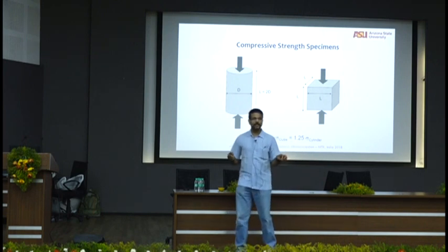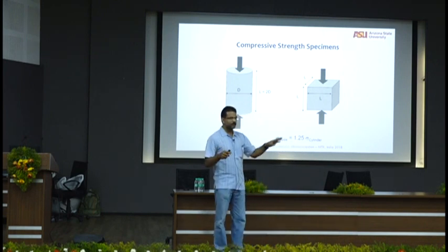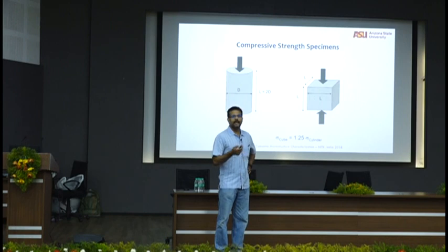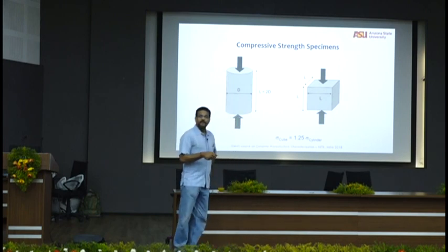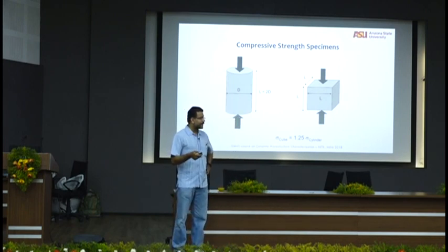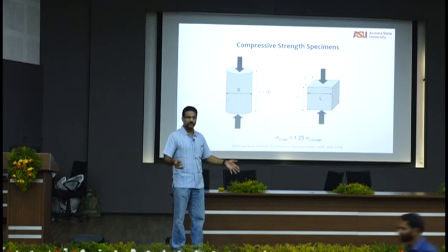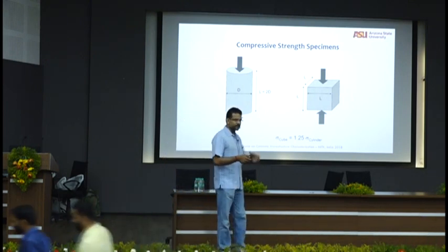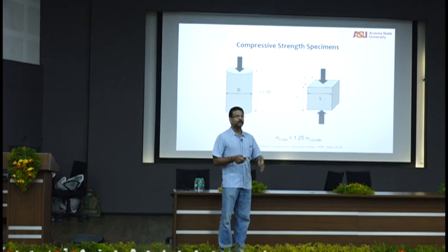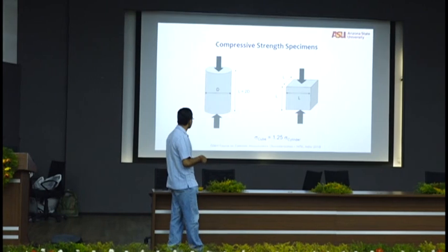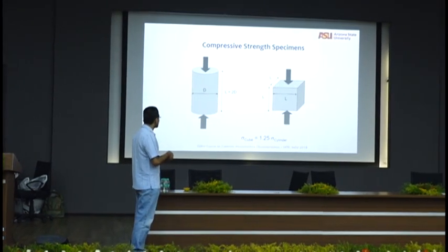The technicians are there actually as technicians. They are working on the machines. They are not helping you make or mix concrete, and we don't have, manpower is very expensive, right? Extremely expensive. So out of practicality, it's impossible for me to carry around 150 mm cubes, very heavy cubes. So 4x8 cylinders, 4 inch by 8 inch, 100 mm by 200 mm cylinders, or 75 mm by 150 mm cylinders, much easier to do. But in terms of mechanical properties,